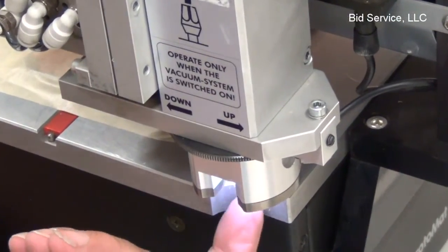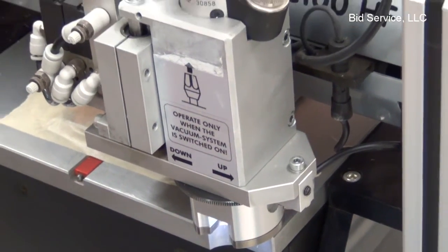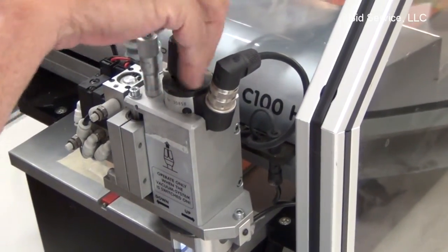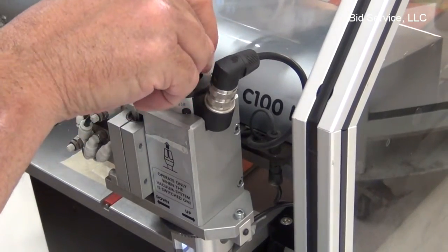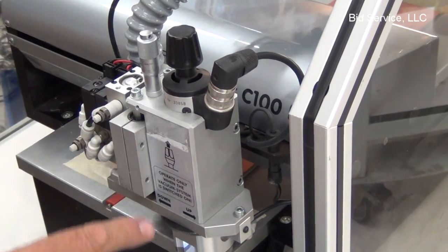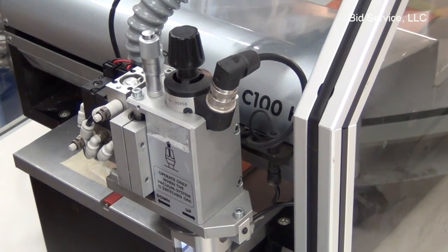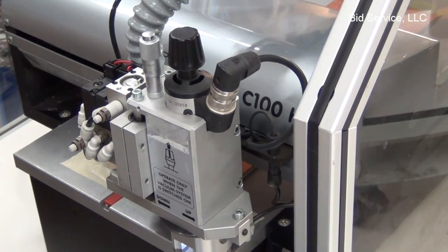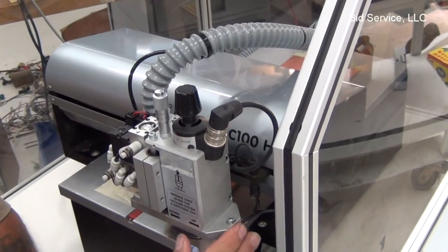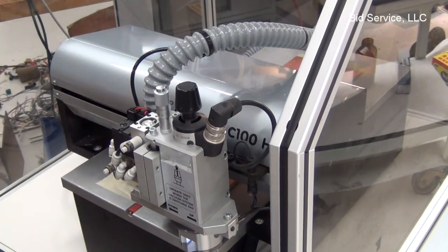You want to make sure that the tool is fully inserted all the way up. Otherwise, your distance of going down is going to be affected. Tighten this knob. And then pull this up again. When it's in the down mode, it's locked, and this actually is free spinning. It won't spin even though the motor is. So you need to make sure that you pull that back up. There's also a micrometer depth adjustment here and a large scale depth adjustment here. That's all covered in the manual. I'm not going to interfere with those during the test.